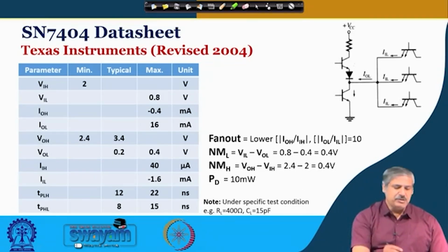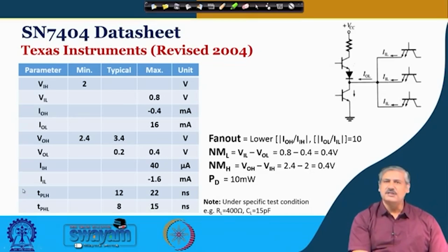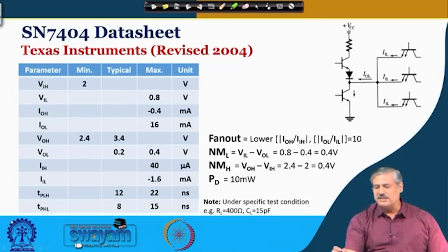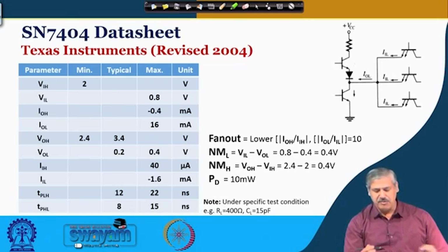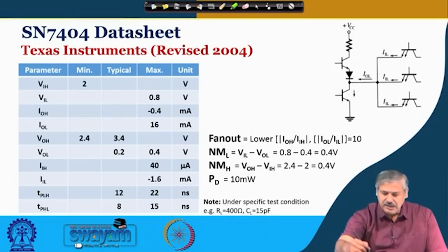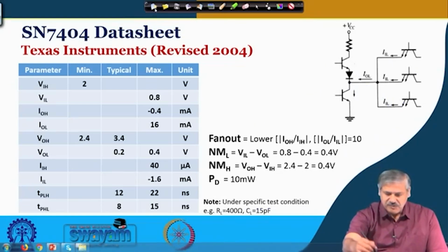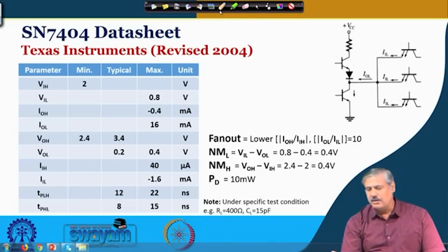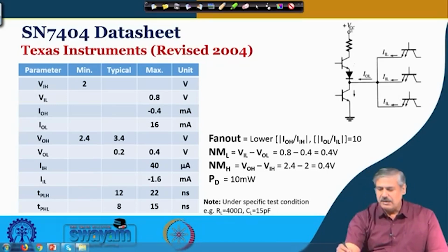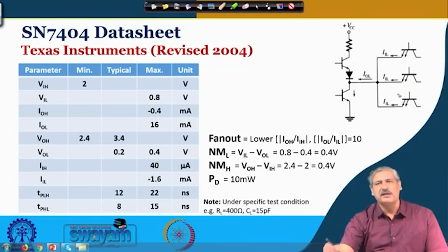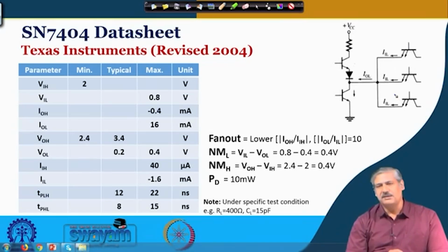In addition, you can see the corresponding current values for these different cases. One such thing that we can see for fan out calculation here is the case where you can see this is the totem pole output and similar gates have been connected at the output.